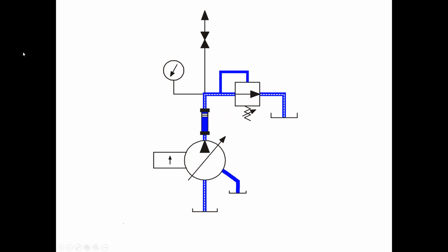Okay? Now, if the pump is any good, we should be able to turn that pressure up on the relief valve and not lose any significant amount of flow. Right? I'm talking maybe just a couple of percent. Okay, so the pump's good. Flow is going to stay high even when we increase the pressure. Now, if you can get up to your normal system pressure with no significant reduction in flow, then there's nothing wrong with that pump. Your problem is elsewhere.